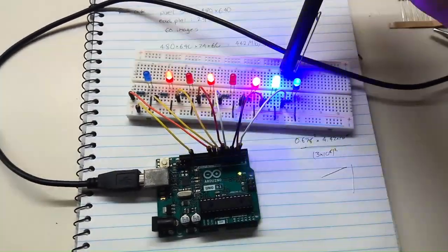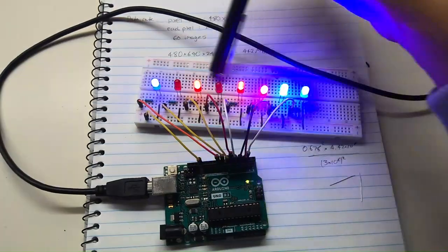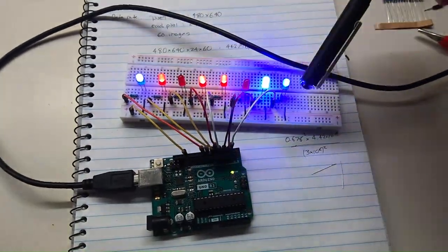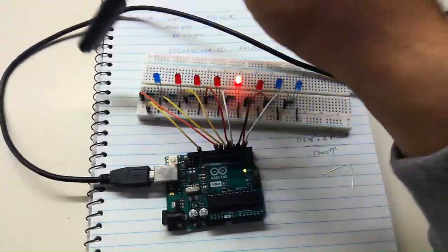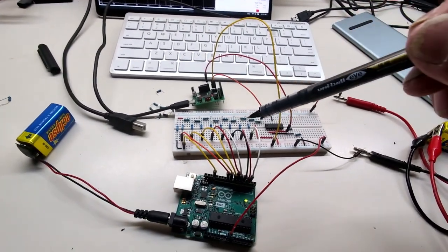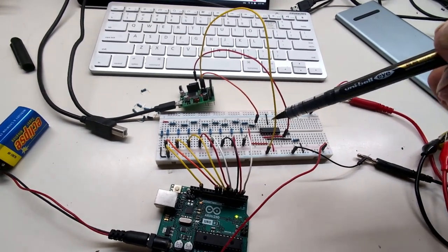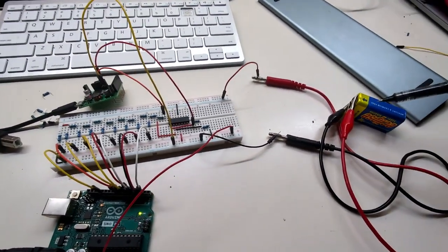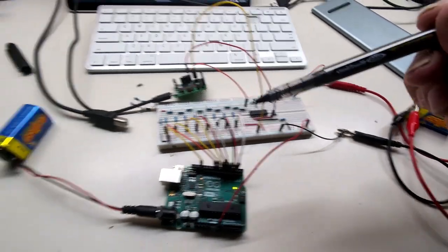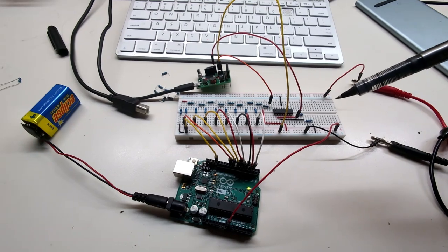Currently this is just cycling through an array of 0 to 255, showing it in binary from the least significant bit to the most significant bit. Here we have the physical circuit, with the output connected to the DAC, and the op amp being powered by -9 volt and +9 volts, so we can output ranges in the negative.